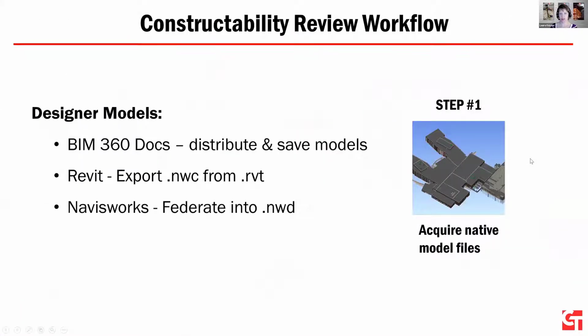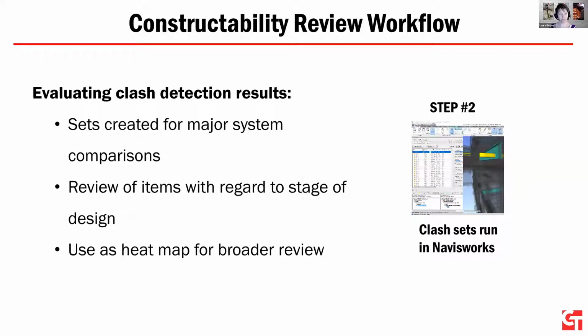Okay, so step one, I think we're all pretty familiar with this. Ratio gave us access to their models, and I'm using BIM 360 Docs, same as what Scott said, just put cloud over top of any of this stuff to ease any confusion between what's going on now. So I was able to get their designer models. I just exported out NWCs. I did make an NWD file in Navisworks so that I could use this issue tracking.